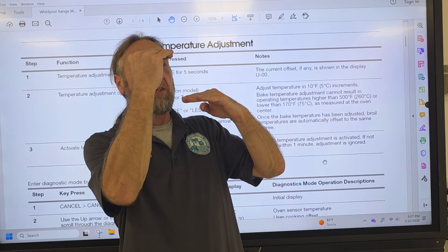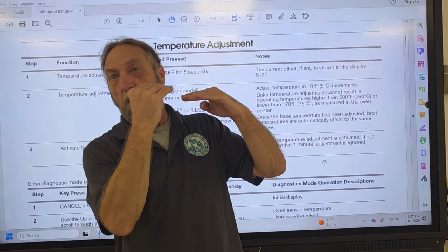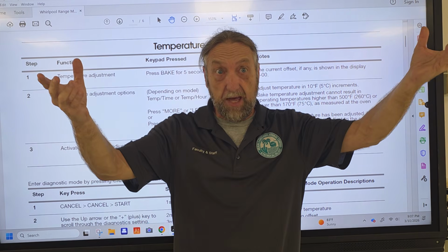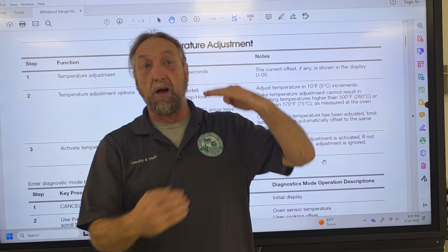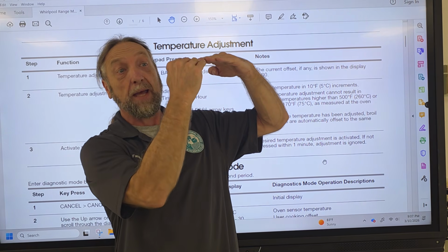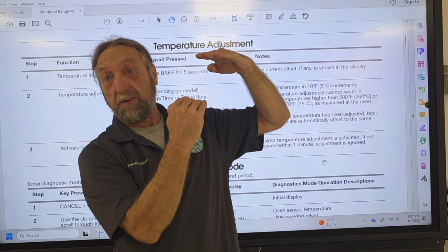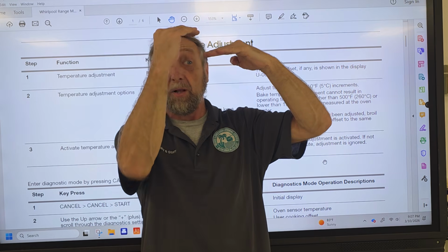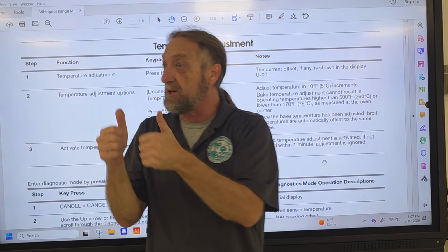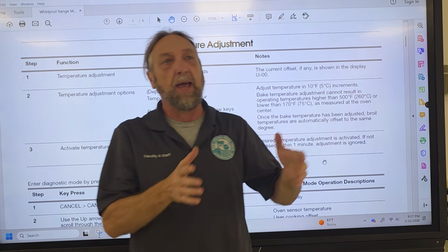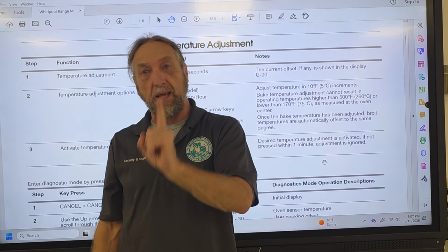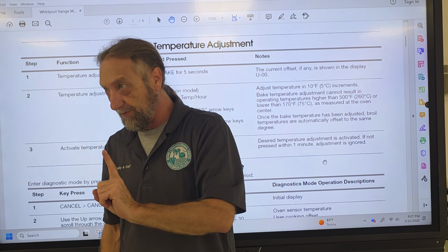But now when the oven's off, the temperature is going to start to drop because the oven vent is allowing some of that heat to escape. We need to turn the elements back on. So as the temperature is dropping and gets below 350, it comes back on, and now it cycles above and below that 350. So you're supposed to take 6 readings and take the average of the 6, but we do not take the first off.